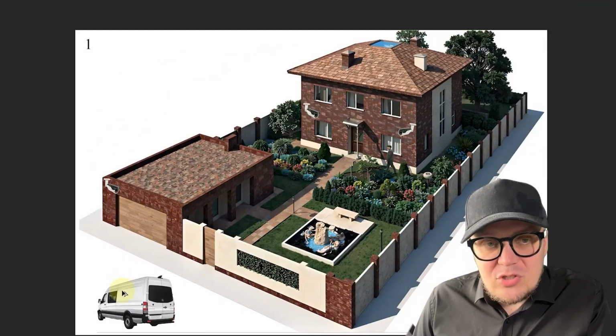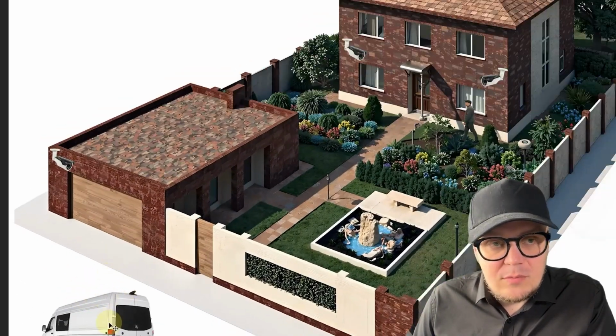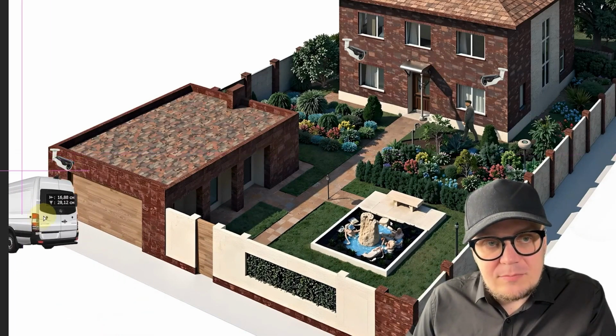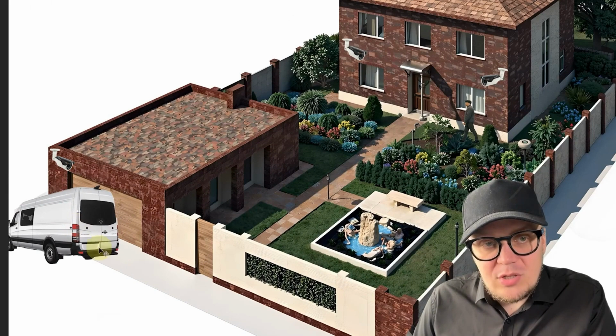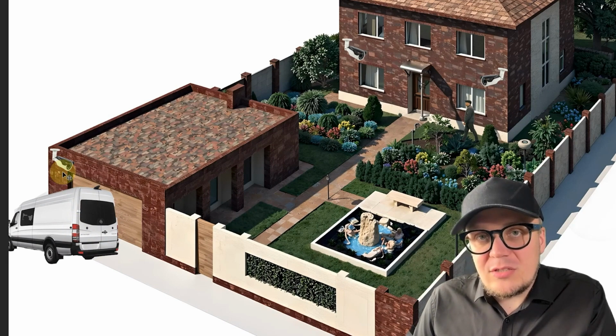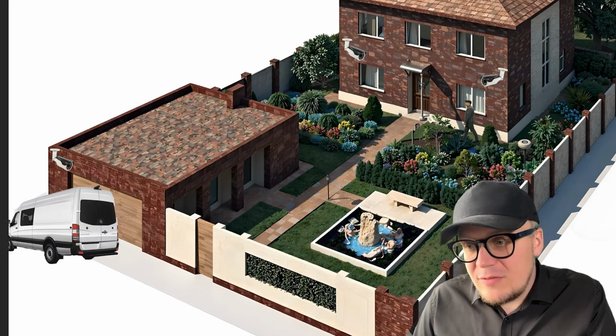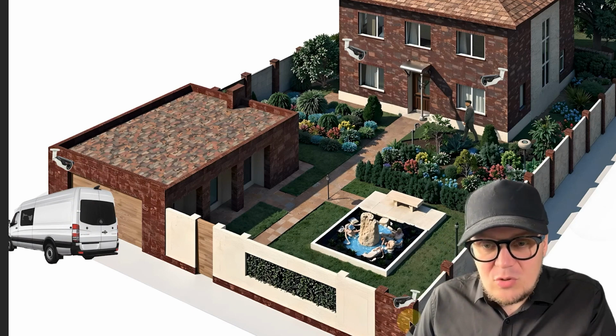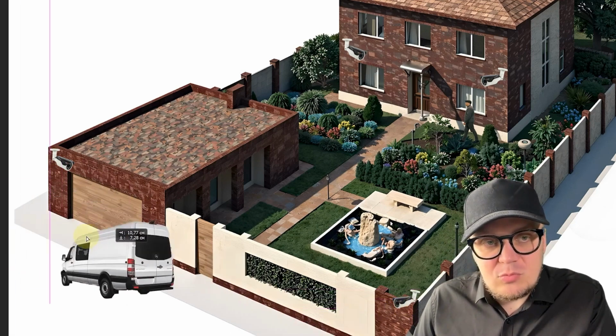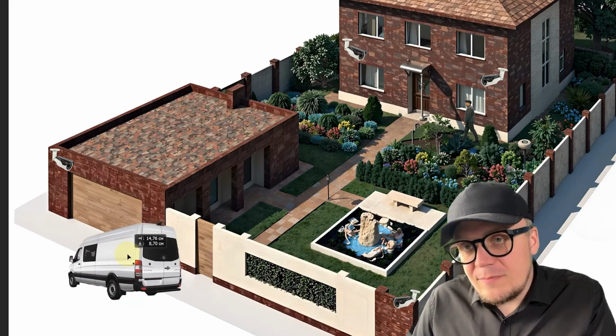The same situation applies to the entrance group. Often the camera is installed like this, and here it can approach like this. A small truck can park and you won't see its license plate. How to fix this mistake? You need to install a second surveillance camera, then no matter how a vehicle passes here or how a person walks by, there will be no blind spot.